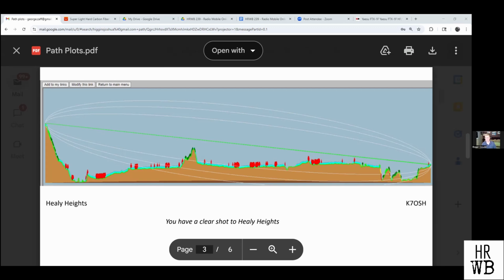As an example, when you do VHF propagation in urban area, you know that you have a lot of noise coming from computers, machines all around. If you drive on the road, you have intermodulation, name it, okay? So you may consider that your threshold is like 5 microvolt.